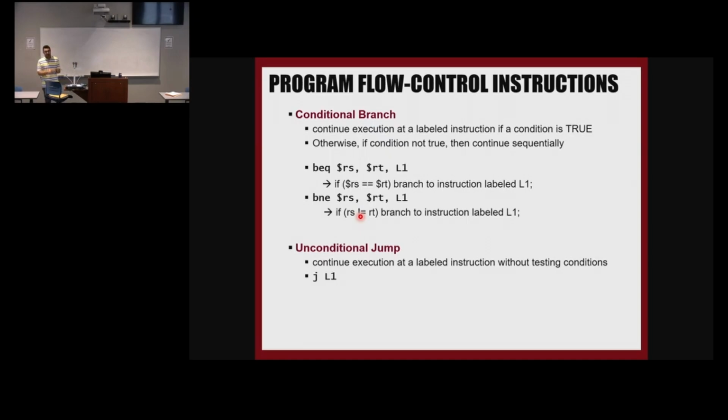It actually has a different kind of instruction type. We have an instruction type called J-type, and that's for jump. That was a design choice in the MIPS processor: instead of using branches, they designed specific hardware to take care of jump. But you could do it, yeah.